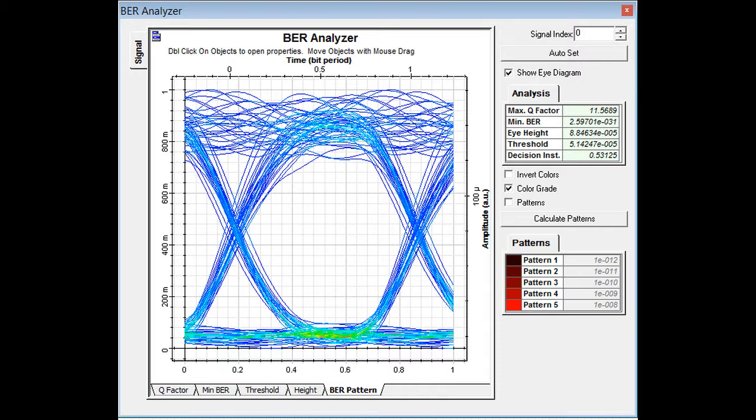The most important challenge faced by this FSO system is fog. Its attenuation is taken as 43 dB/km. In the FSO system under fog with the same other conditions, it is seen that the Q factor of the single TX-RX FSO system is decreasing, which can be improved with a 4TX/4RX FSO system.